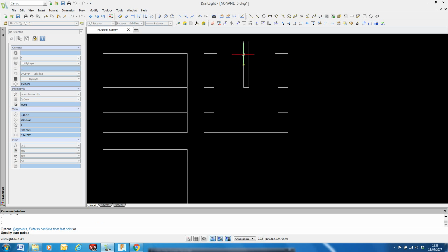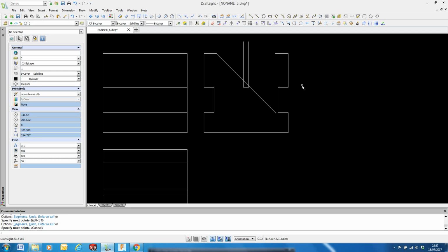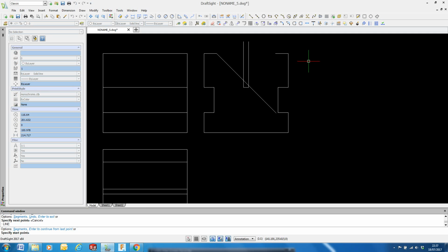and now we could get into some polar relative coordinates. We have no idea how long the radius is, so let's just make it long. So thinking about it, that's my start point. Relative at the length of the line, I've no idea. Let's go 50 radius at an angle of 0, 90, 180, 270 and 45 degrees, 315. So at 50 at an angle of 315. Escape.